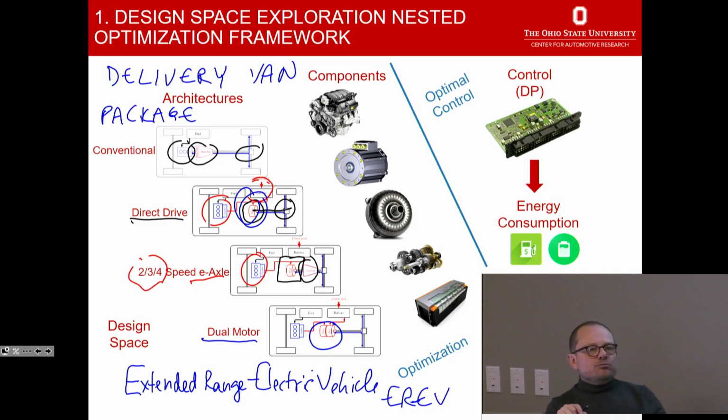If I have 2 smaller electric machines, I can use one or the other. Maybe I alternate between the two when I'm at low speed, low load, because the smaller machine will operate at a higher efficiency point. So I could, in principle, have better efficiency overall if I have 2 electric machines.